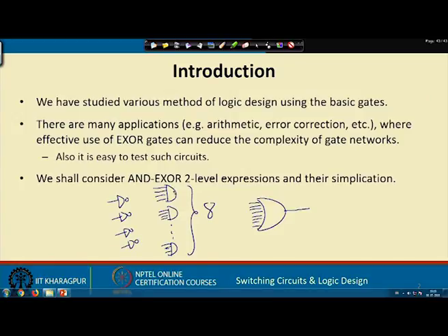So, you see you will be requiring 8 4-input gates, 1 8-input gate and 4 NOT gates for a conventional AND-OR-NOT realization. But if you use XOR, you need only 3 2-input XOR gates. You see, this is a classic example which shows that XOR gates for some applications can be very, very efficient as compared to conventional logic implementations.